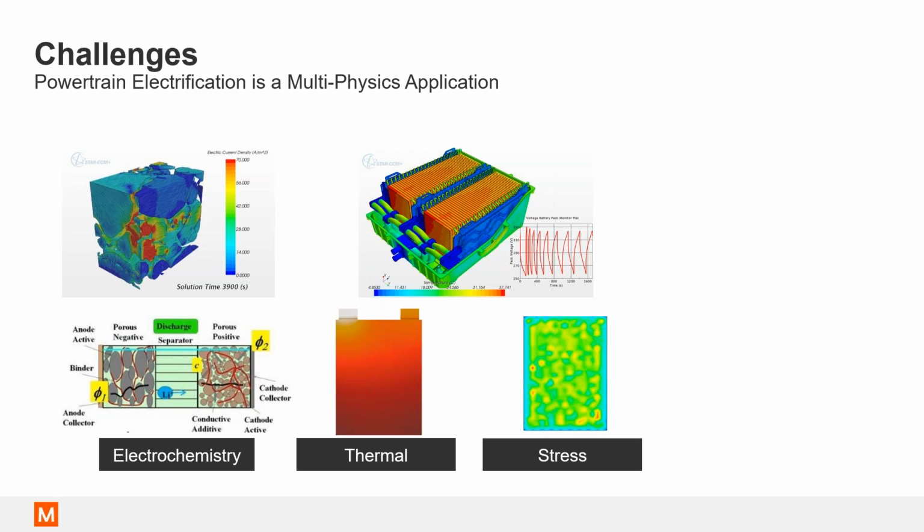At a pack level design, one would want to understand the effects of my drive cycle on the thermal load, as well as, if it's a stack-based cell, there would be expansion and contraction, or cell breathing, which creates stress. And how can I mechanically control that stress by including braces, and what should be the pressure that I need to account for?